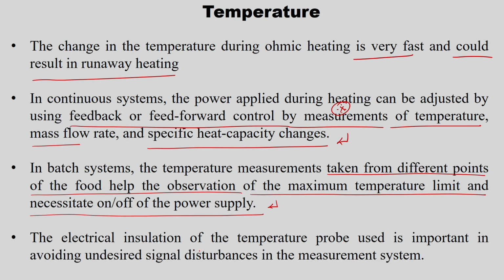The electrical insulation of the temperature probe used is very important in avoiding undesired signal disturbance in the measurement system. What we are using is electrical energy to heat the fluid. In such a case, the temperature probe we use should also be insulated properly, otherwise it will have undesired signal disturbance, because this is electrical and that is also electrical. So the insulation of the temperature probe used for the temperature measurement should be proper.